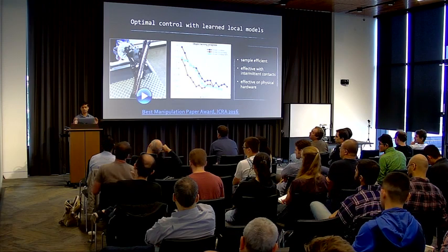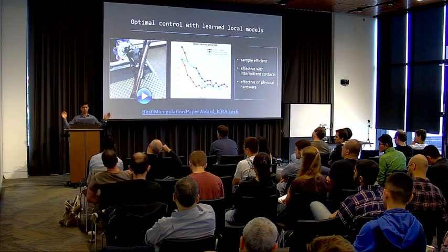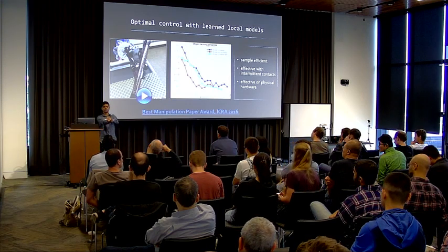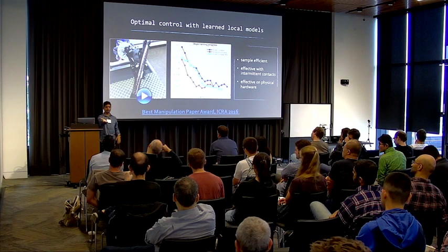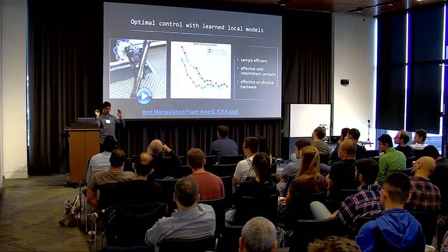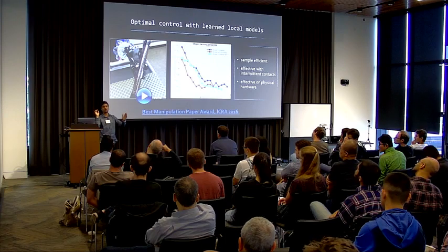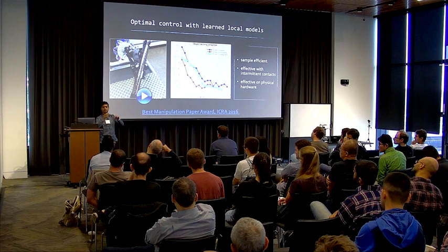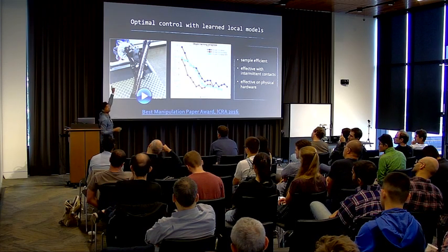I see. So directly on the real system, from step 0, the first data was collected by a random policy with the object on the hand. But you have part of the model, like with your actuators and sensors? No, nothing. The input to the system is completely raw potentiometer values from the joint angles, and the action space is a little more convoluted over here because we are going through pneumatics.